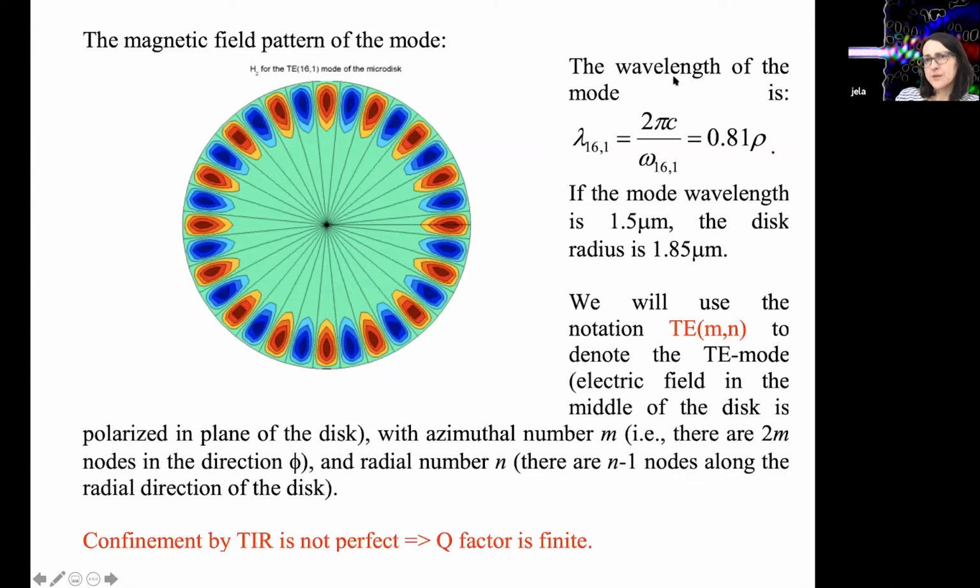And in this particular case, knowing all the parameters of the system, you remember the problem that you're solving is picking the diameter for the disk if you were constrained with having indium gallium phosphide material with 220 nanometer thickness, and you're building a laser for 1550 nanometer operation.